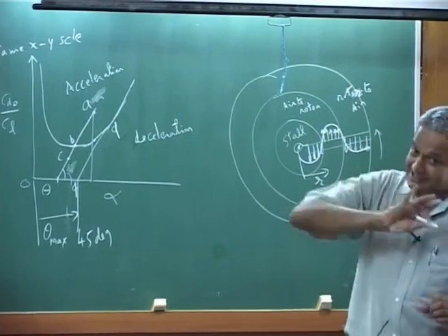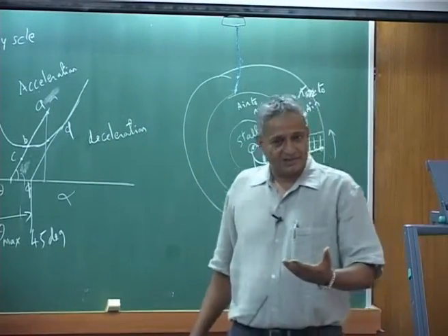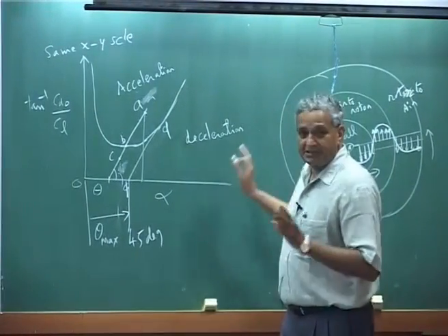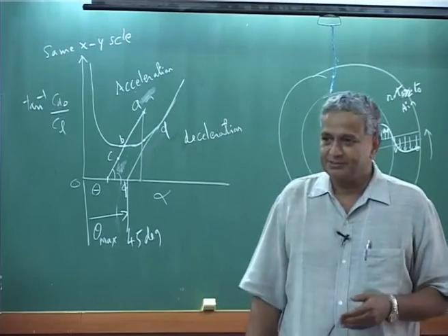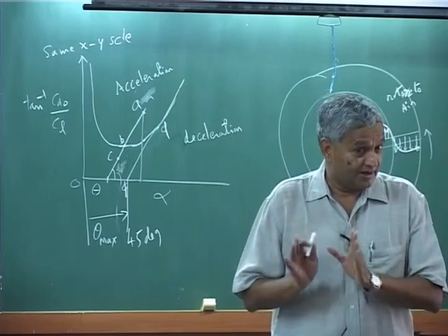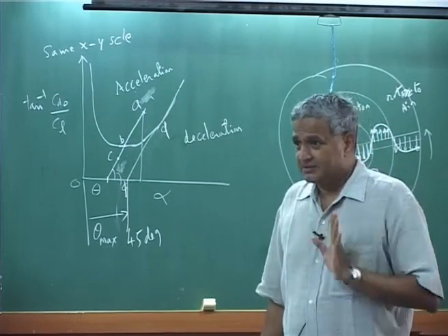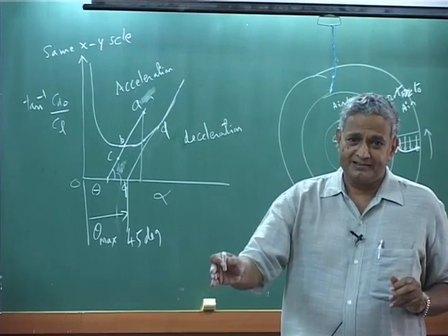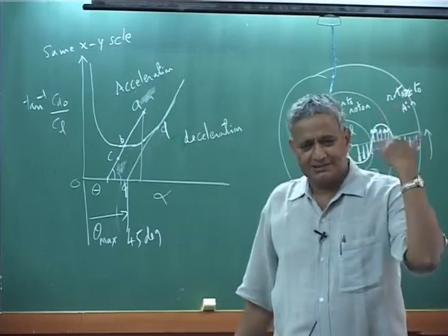That is why you have to integrate along the blade, knowing the characteristic. Otherwise, mostly in the industry they may take, in my opinion, a typical section. Typical section in helicopters is about 70% or 75%, but I do not know for autorotation whether they take that value. It could be even 60. I do not know, you may be able to tell me. For that section, you satisfy this. After that, the rest of them take over.